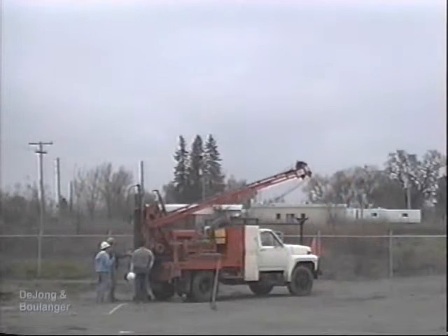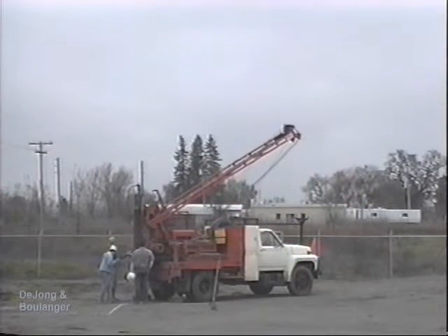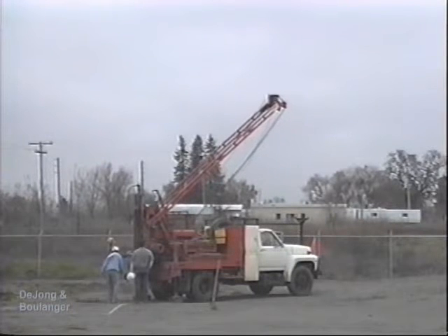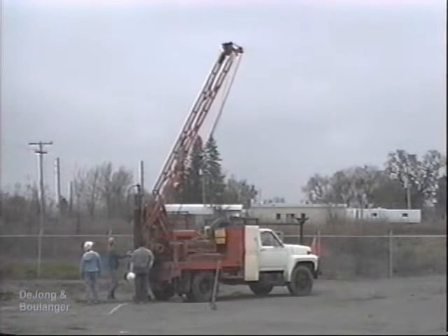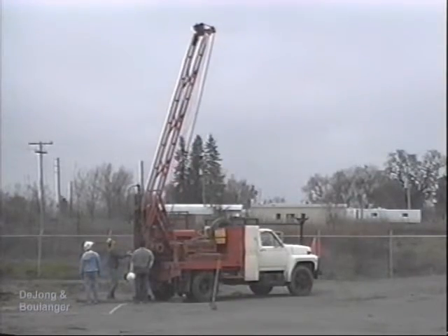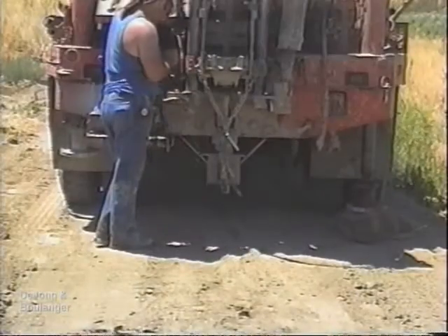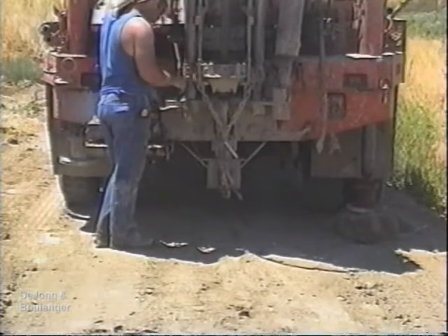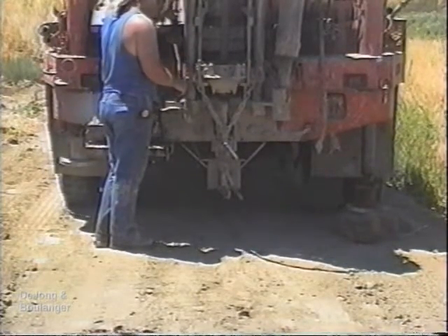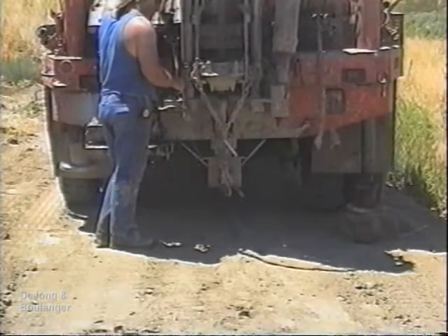Here a highway drill rig will be used to demonstrate the general features and procedures that are common to all drill rigs. After the drill rig is positioned over a borehole location, the mast is raised and secured and the drill rig is leveled. If the rig is not level, the borehole will be angled, causing great problems in drilling and sampling, in addition to producing an inaccurate soil profile.